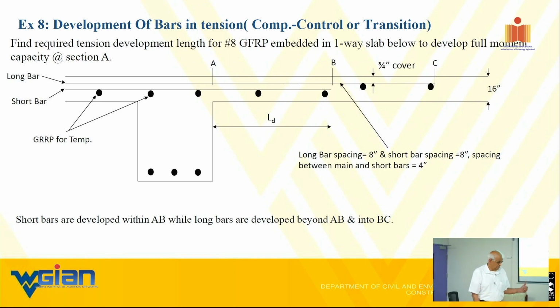I don't know whether I showed you, we have rehabilitated a bridge, a 42-foot high column that had a gaping hole all the way across the length of the column, and then we did the rehab of that with carbon wrap. That bridge is a skewed bridge, and it is on a slope, all kinds of things. Therefore, we went with carbon.